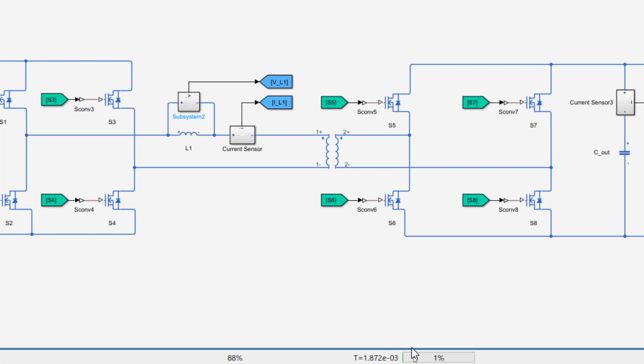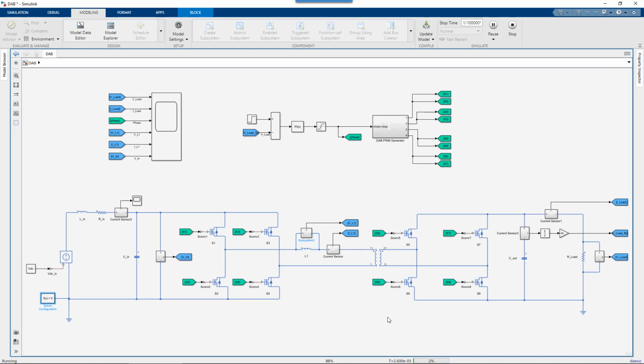So if I crank this down and get good results when everything else was getting bad results, that gives me an idea that, okay, there's something that we call stiffness in the system. So you may have some really fast RC time constants or something like that, or you're modeling some snubbers you don't need to, just some values that are creating really high frequency content that is messing with your simulation that's not really relevant to the quality of the simulation.